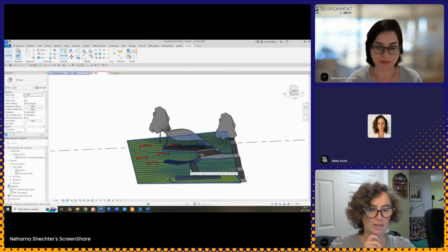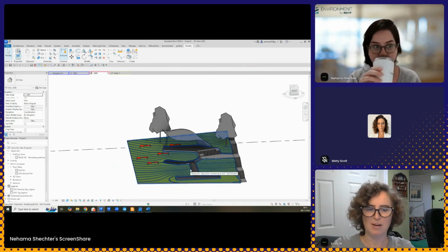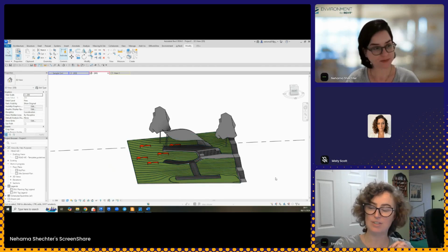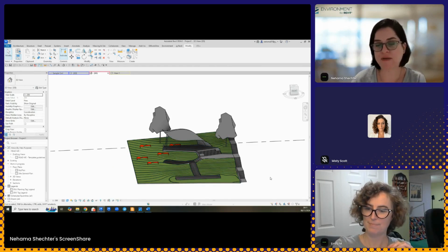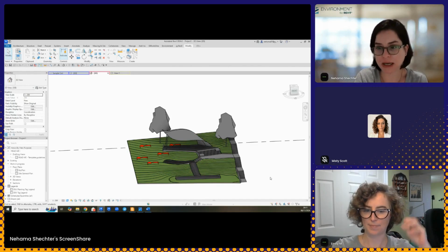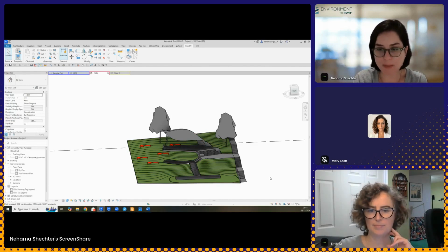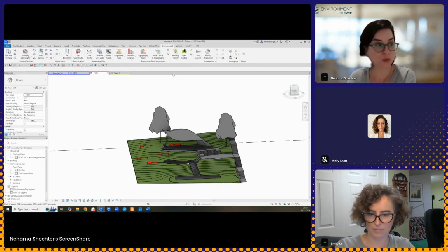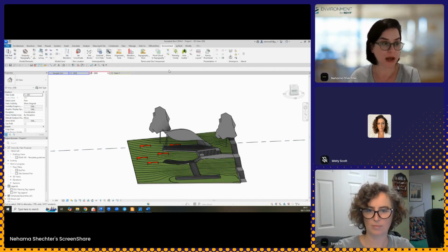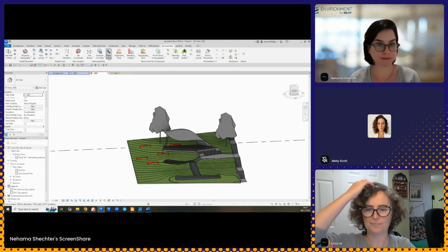Yeah. Well, so you mentioned materials there. We've got a question. It says, how do you recommend handling material adjustments when importing Rhino models, particularly if the textures are detailed or unique? So if you have a unique material in Rhino, that's still something that we haven't figured out. So I think the best thing would be to actually duplicate it and take the texture and create a similar material in Revit and then assign it.